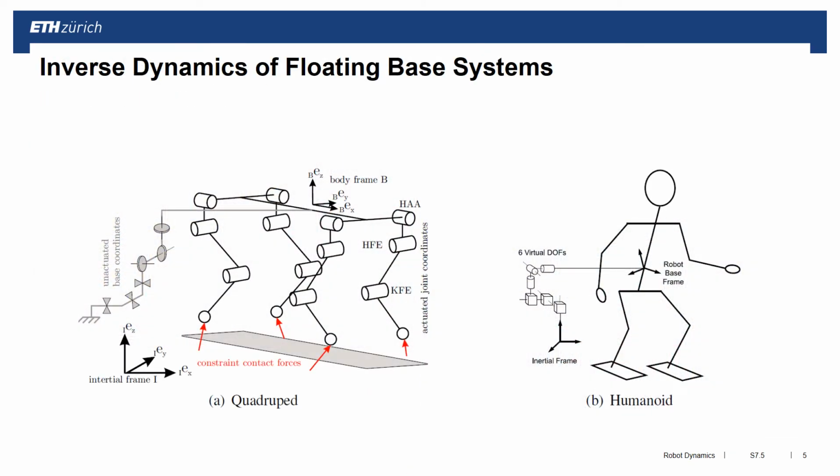To achieve this, what we want to do is inverse dynamics control with floating-base systems, so systems as we see in here. And again, the big difference is that these systems are in contact with the environment, so we have to consider also the interaction forces with the environment.